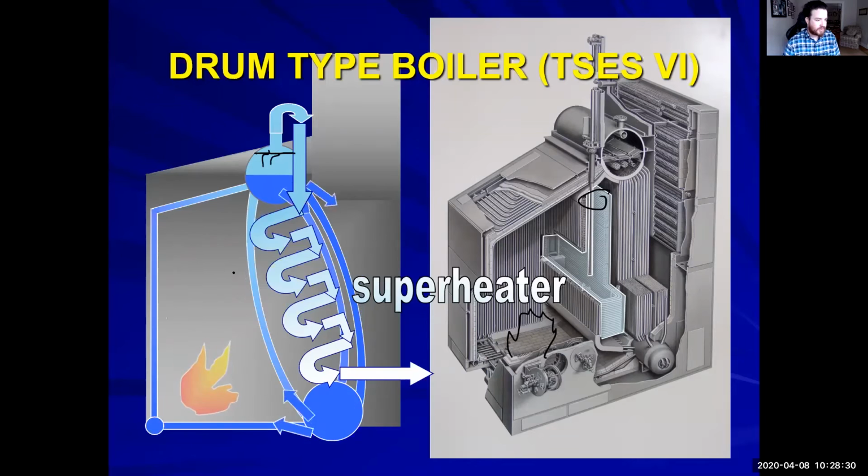All right. The superheater is going to superheat the steam. It's already at 600 psi, but now we're increasing the temperature to ensure that there are no water molecules present. No liquid molecules can be present in this. Just like going into the compressor of our refrigeration cycle, if a water molecule impacts a turbine blade, extreme damage happens. You'll learn about it in your turbines class, but there is a huge amount of damage that will happen. And that's what we're doing. We're protecting our turbines.